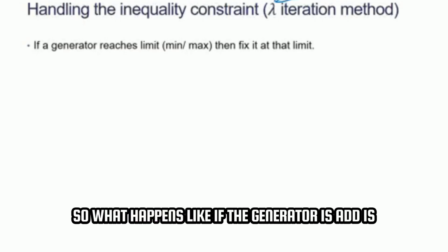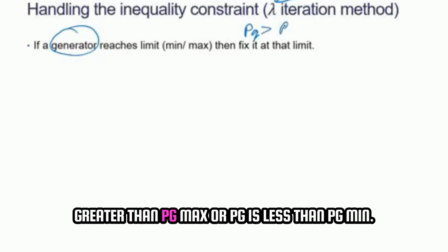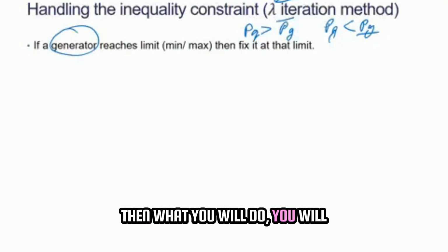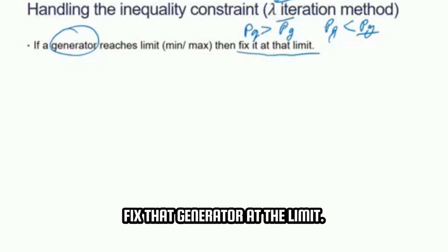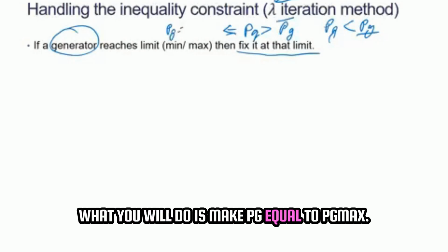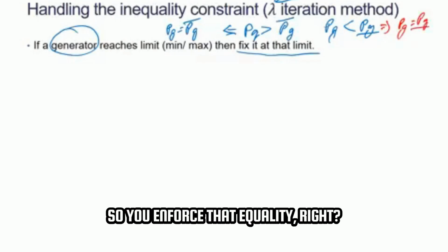So what happens if the generator is crossing its limits, or basically if Pg is greater than Pg max or Pg is less than Pg min, so basically it is crossing the limit? Then what you will do is fix that generator at the limit. So if this is the situation, you make Pg equal to Pg max, or if this is the situation, you make Pg equal to Pg min. So you enforce that equality, right?